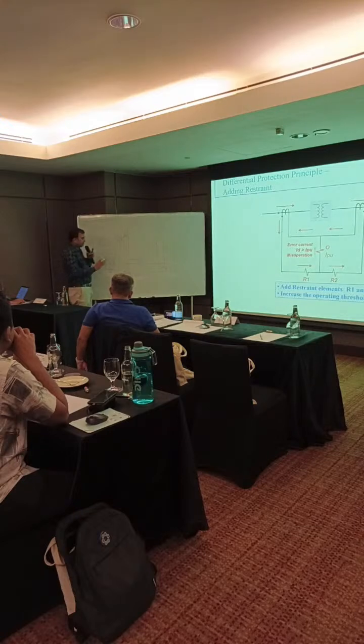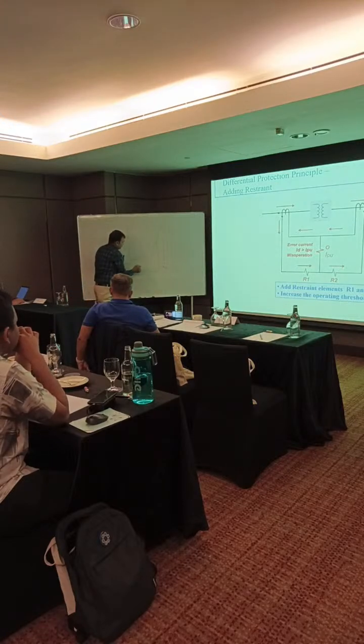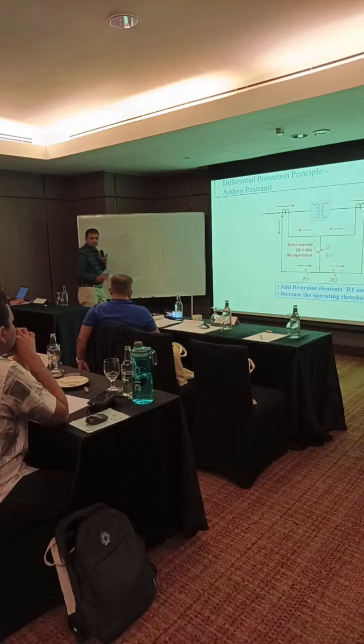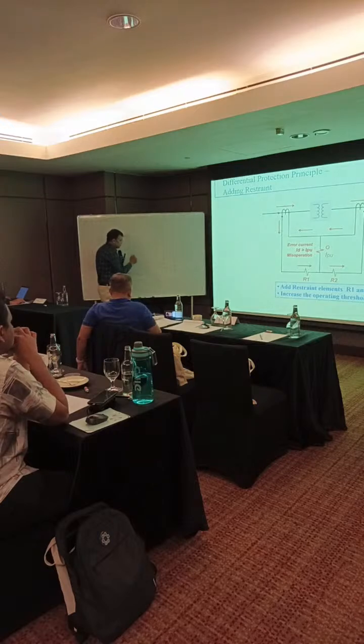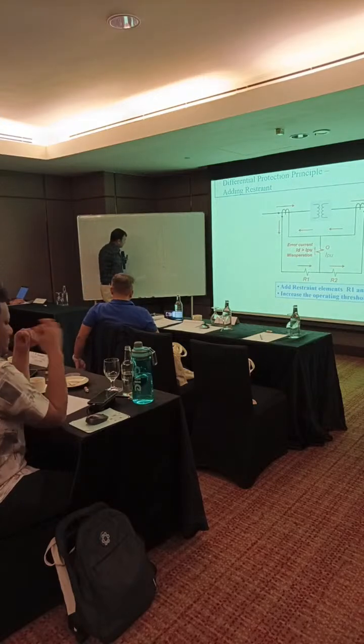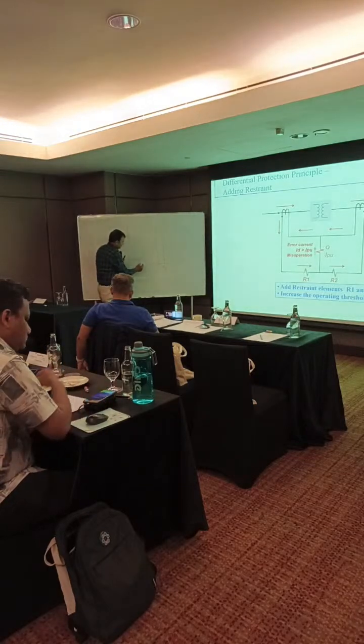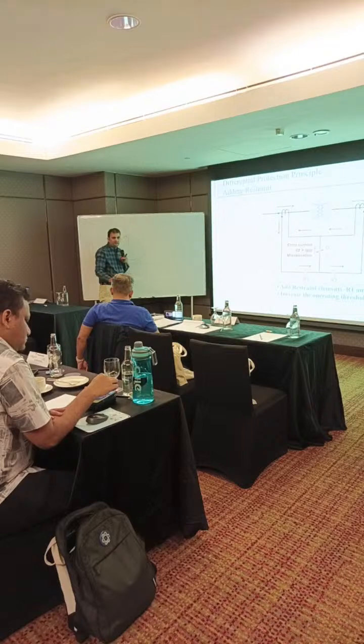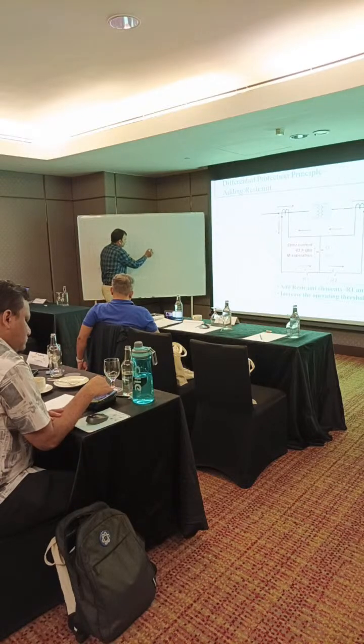Okay, so the only thing we have to keep in mind during manual testing is we should follow where the I bias is starting, at which I bias, which slope is being followed. So suppose we want to test this slope, then our bias current should be between 1 to 1.5. Okay, so we will take 2 points, 1 point here, 1 point here.